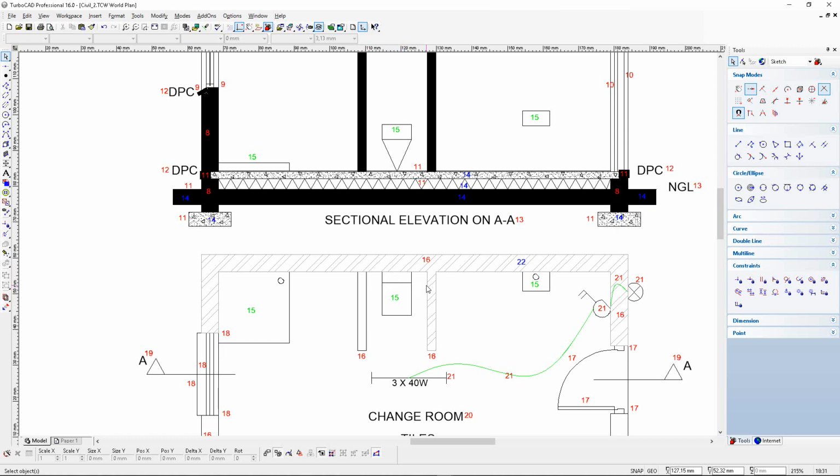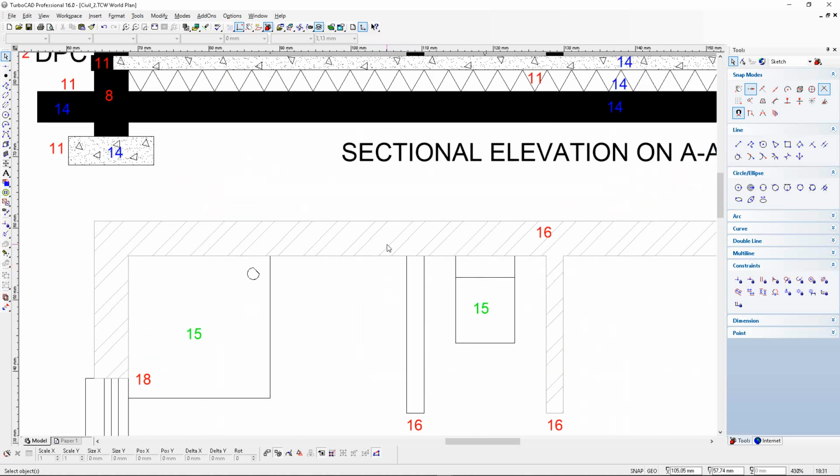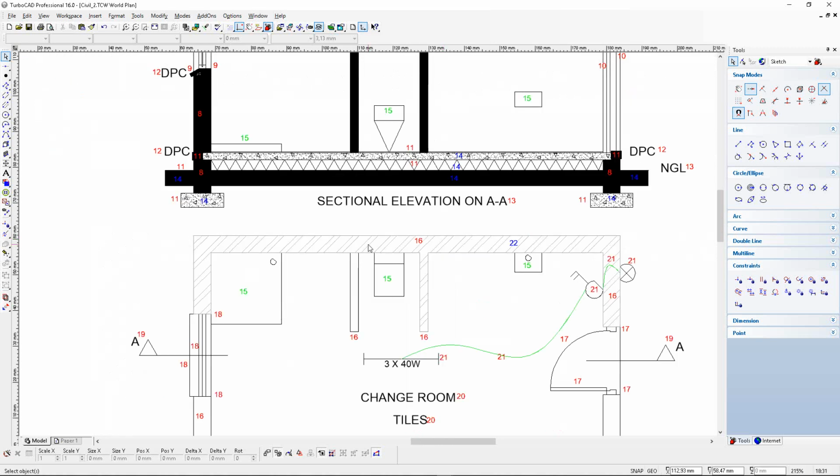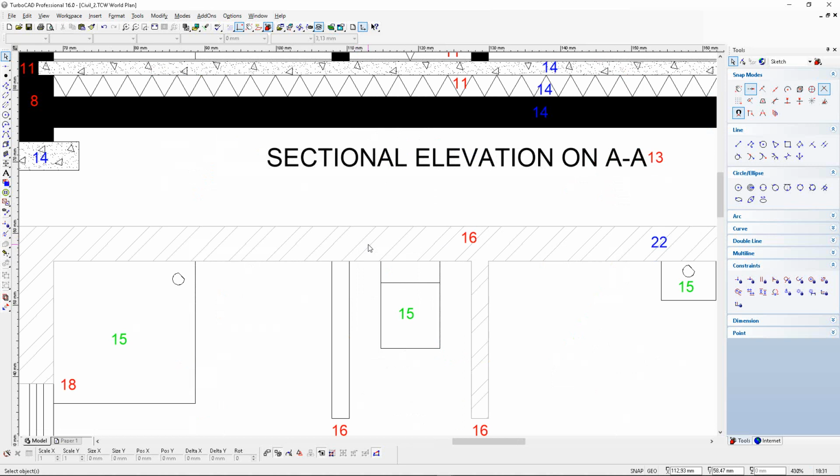For paper drawings, obviously, this is also too close to one another. On paper, you will have to do only every second double line. But in TurboCAD, this is perfectly fine because obviously that is the only way that you can do it in CAD, unless you now obviously go and draw all of these 45-degree double lines yourself. But obviously we want you to use the hatching tool.